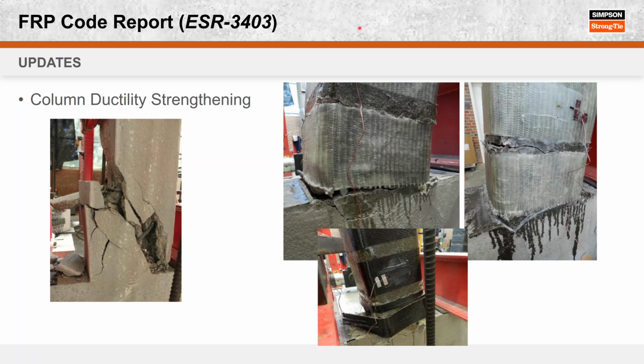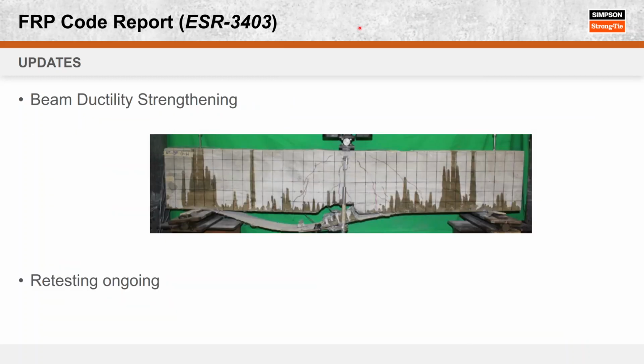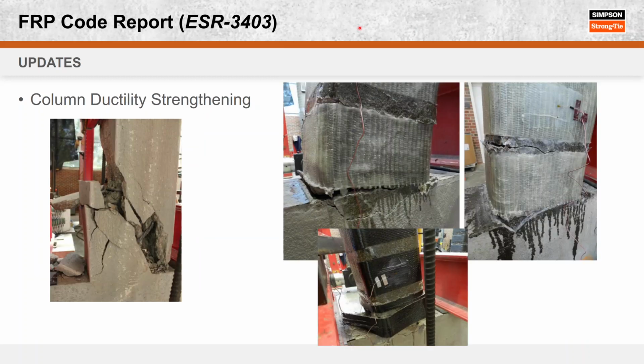There's not a specific ductility test we had to do. And I think actually these are the shear strengthening specimens I included in the picture. I didn't actually show a flexural one, but the flexural ones were basically just either a 12-inch or 24-inch wide strip at the bottom of the column only, just in the place it would fail.